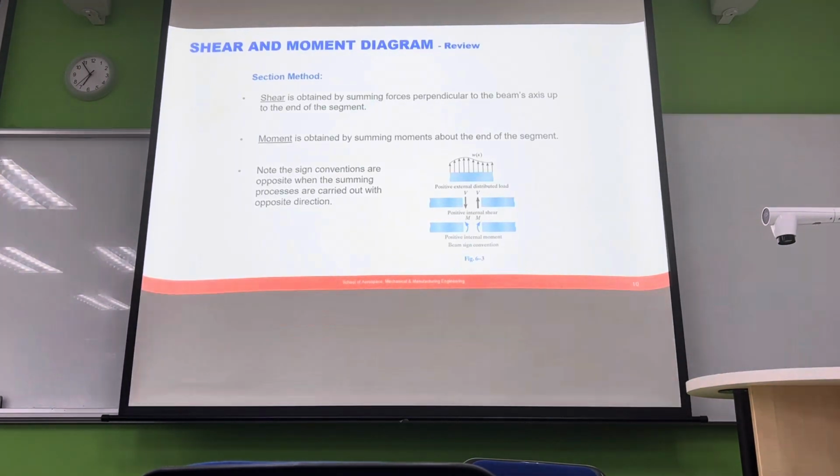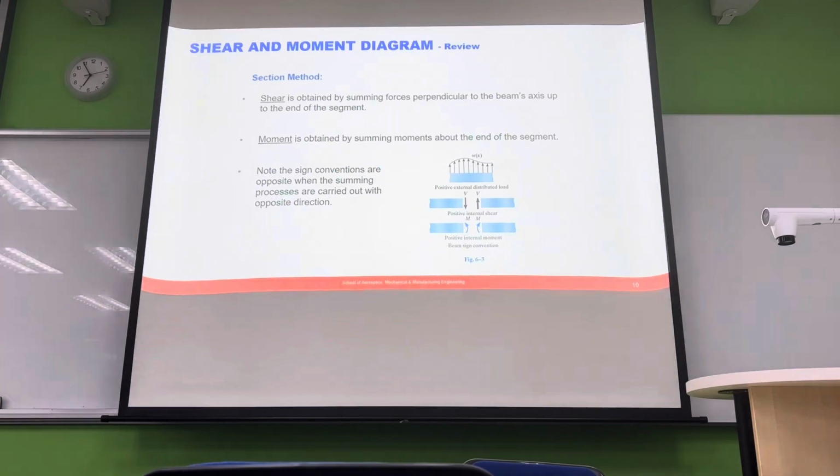Shear forces are obvious because if we have some sort of force here, equal and opposite reaction, there need to be internal forces to oppose it. We call those shear forces V, and this is how we define it to be positive. If I've made a cut, and if I'm looking on the left-hand side of that cut, downwards is positive. If I'm looking on the right-hand end of that cut, upwards is positive. And if I just look at that left-hand side, this internal shear force here has to be enough to balance out all of these forces, as if I cut it that way.